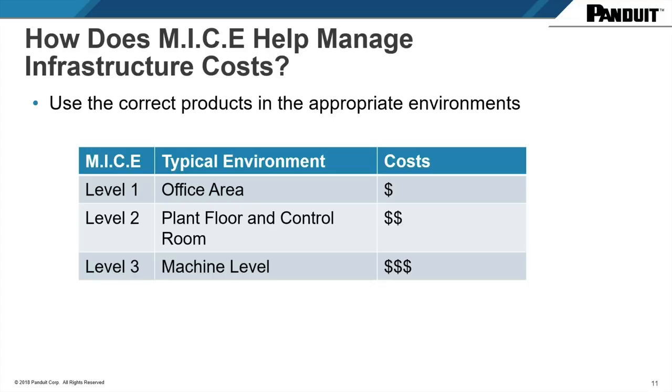We try to apply the M.I.C.E guideline everywhere possible in an industrial space to give us the best protection for our cables and connectors. And we have to be cognizant of these costs. So if, for instance, a certain solution is very expensive to apply in a certain area, we will try to find out if there are mitigations that we need to apply to protect that device at the edge point.